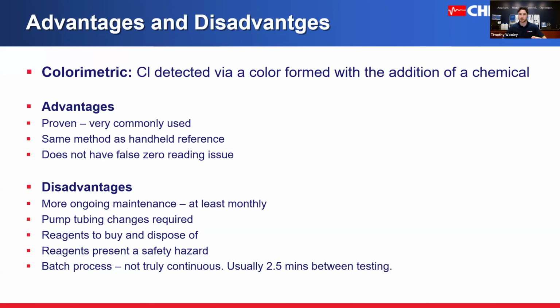As we covered, you need to change out the pump and tubing that pumps those reagents into the water. And these reagents do have the potential for things like skin, eye, and respiratory irritation. So it's important to be careful when handling these reagents. They do present a bit of a safety hazard. And the last thing I want to talk about is that they are not truly continuous. These measure chlorine about once every 2.5 minutes.